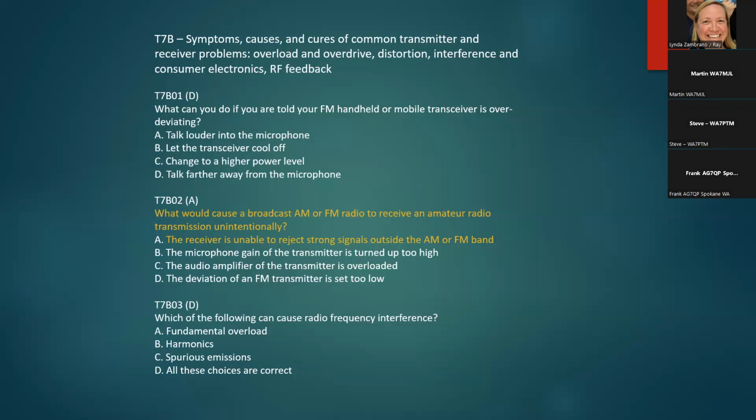And you would think that the 100 megahertz AM or FM receiver wouldn't actually receive it. But if the signal is very, very strong from the transceiver at the FM radio, it can overload the circuitry in the radio and actually receive the transmissions that are being transmitted 44 megahertz above the actual frequency that the radio is set for.